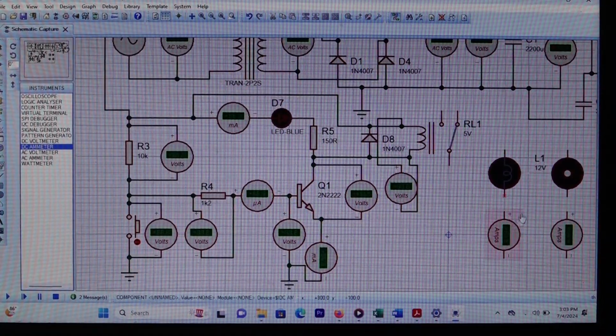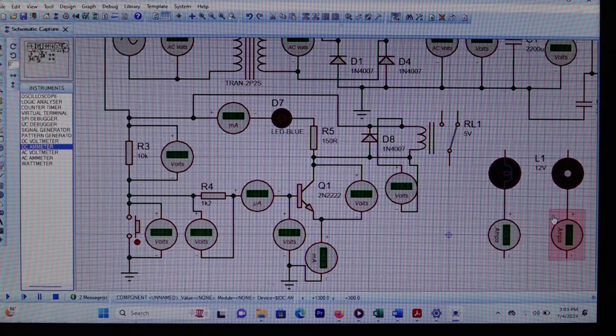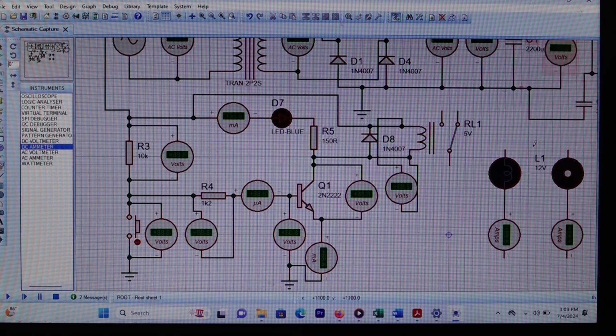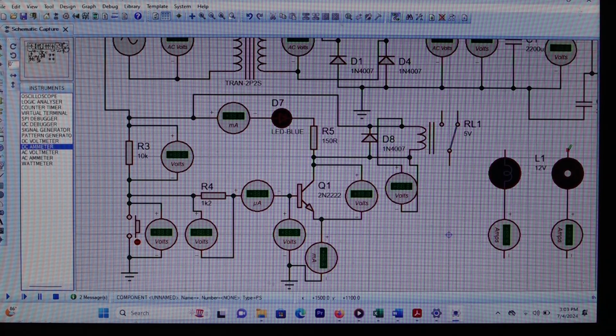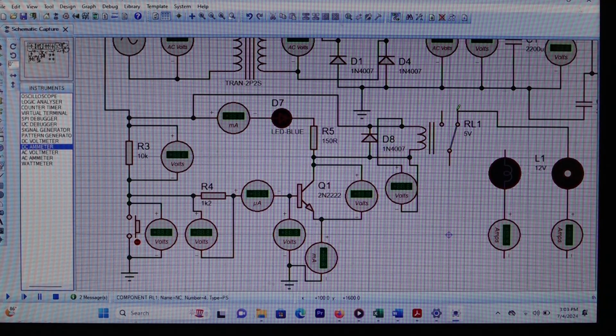Okay. So now let us connect the lamp with the DC ammeter and connect the DC motor with the DC ammeter. Then we are going to connect this DC motor with the terminal that we call normally closed. But remember that the load needs power.